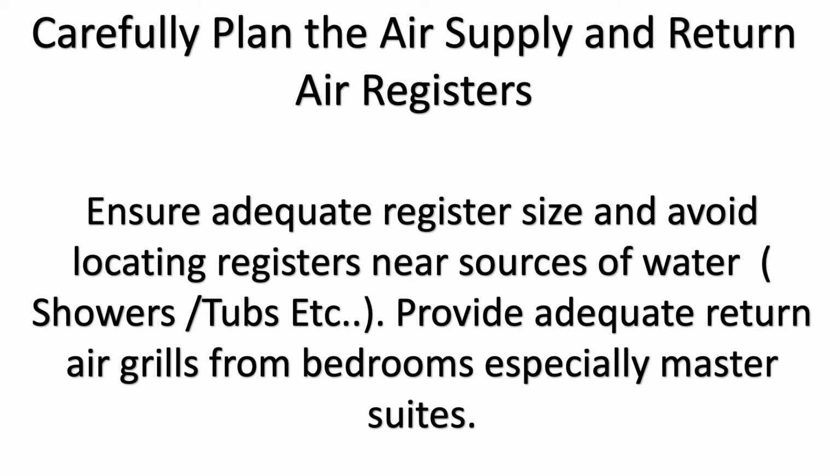Carefully plan the air supply and return air registers. Ensure adequate register size and avoid locating registers near sources of water, for example, showers and tubs. Provide adequate return air grills from the bedrooms, especially master suites.